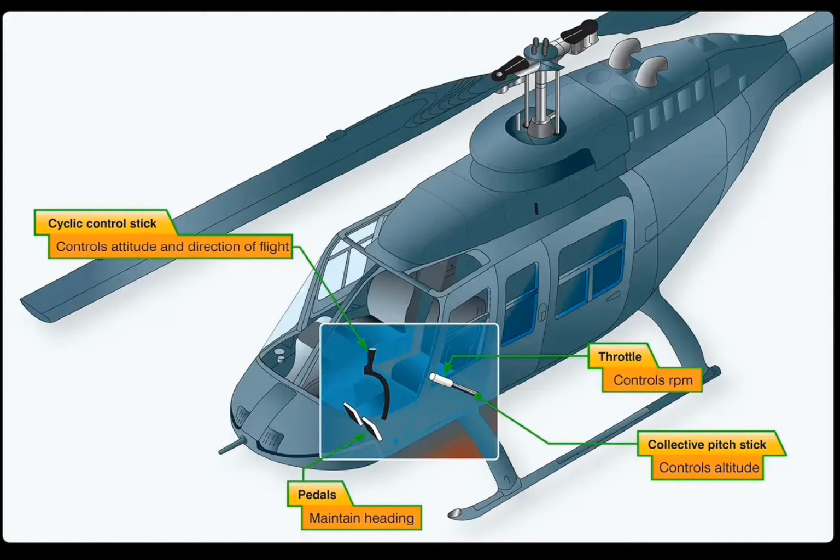Size of the cable, the outside temperature. Why do control surfaces need to be statically balanced? Severe flutter. What tool can be used to measure control surface travel? Protractor.